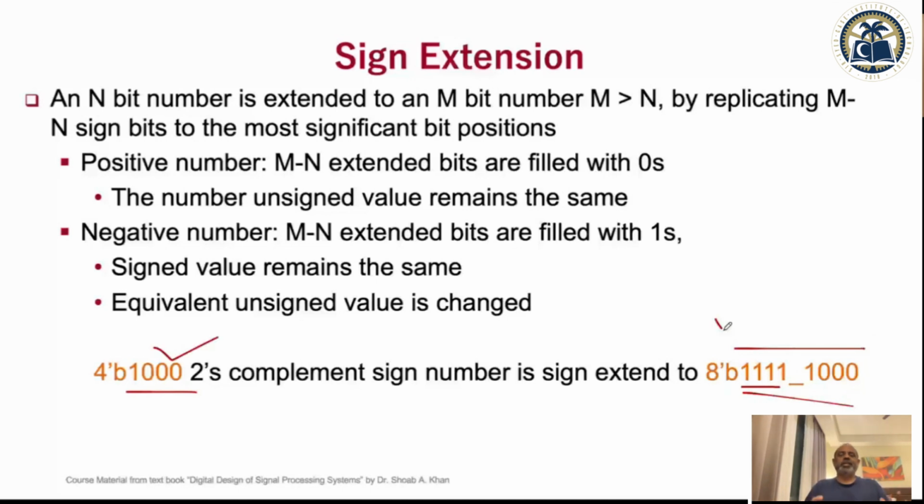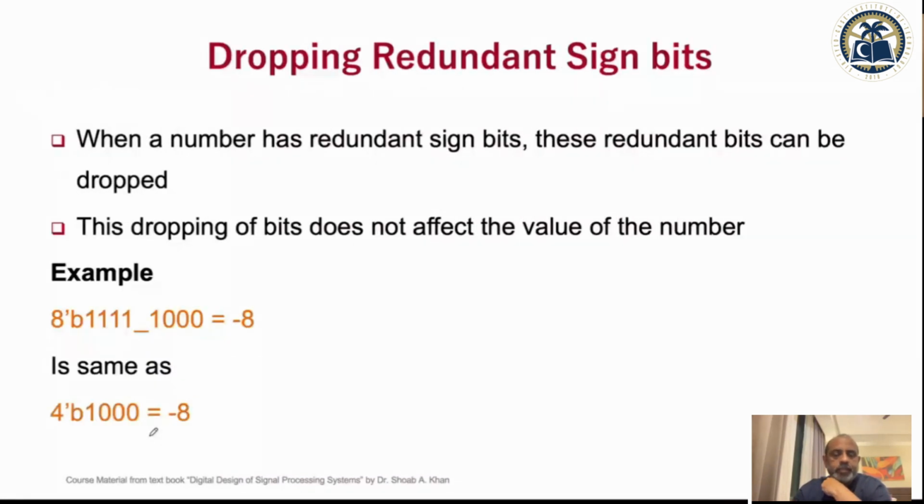Okay. So as an unsigned number they have very different values, but as a signed number they are the same. So this type of confusion, especially when you are looking at your simulation, and the simulator is showing every number as a positive number again, causes you a lot of problems figuring out what the actual number is. But remember, once you are scaling, sometimes you drop all the redundant sign bits. Any bit after a string of ones is not adding any value to the number. So many zeros or many ones on the left in the sign bit means that you are wrongly representing your variable. It does not have that much dynamic range.